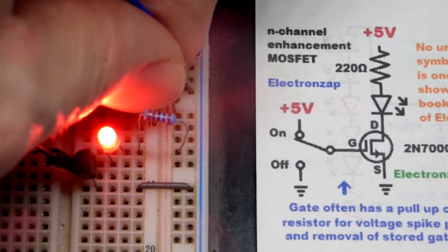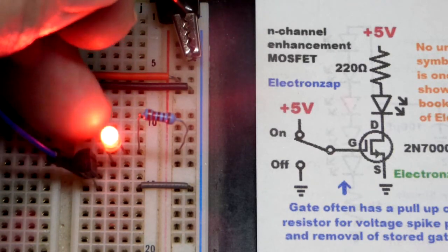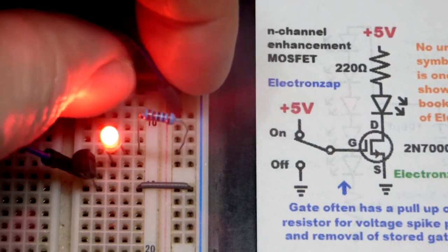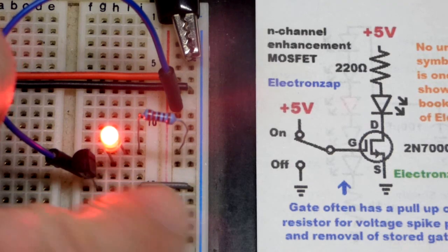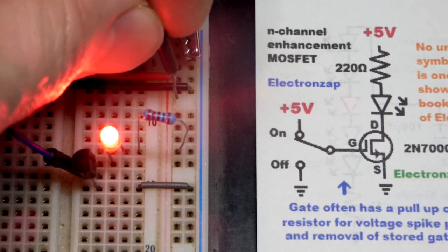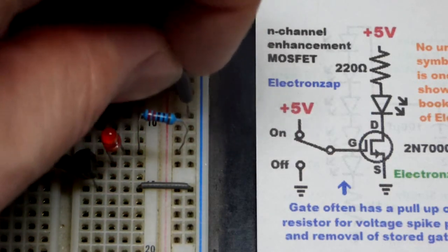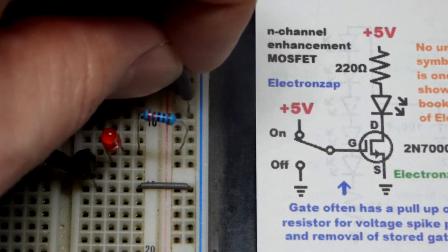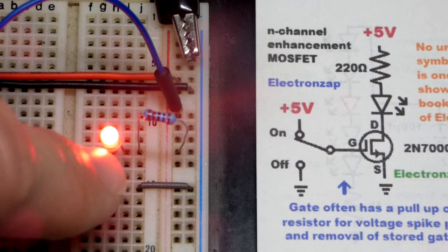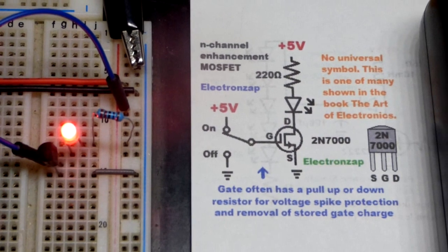So what a pull up resistor would do would mean that the LED would be on. If I yank this out, it would still be on completely with the pull up until I go to the negative supply. That's the only way I would be able to turn it off if there was a pull up resistor. If there's a pull down resistor going to the negative supply, then right now it would be on because I'm to the positive supply, but when I'm floating, that would automatically turn it off, because it's making a connection to ground through a resistance. And the reason why it has to be through a resistance is so I can make a direct connection to the positive supply. That'll make the gate positive, and a little current will trickle down to ground if we had a pull down resistor. So hopefully that makes sense.